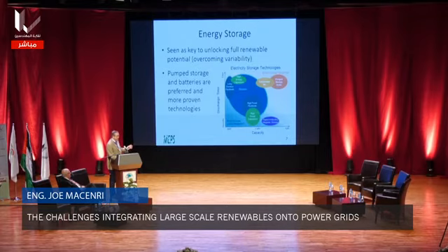Well, one in particular has been around for decades, and that's pump storage. You can see it up there on the top right of the graph. Many power systems around the world have it. Ireland has a pump storage, which is a lower lake and a lake at the top of a mountain, and in the mountain is a number of turbines, and basically just by pumping the water to the upper lake, you store it, and then it's released through that. It's around a 250 megawatt pump storage facility in Ireland. Many other power systems around the world have them. They're not just used for energy storage, but they're used for operational flexibility of the power system, and it's extremely important in Ireland.